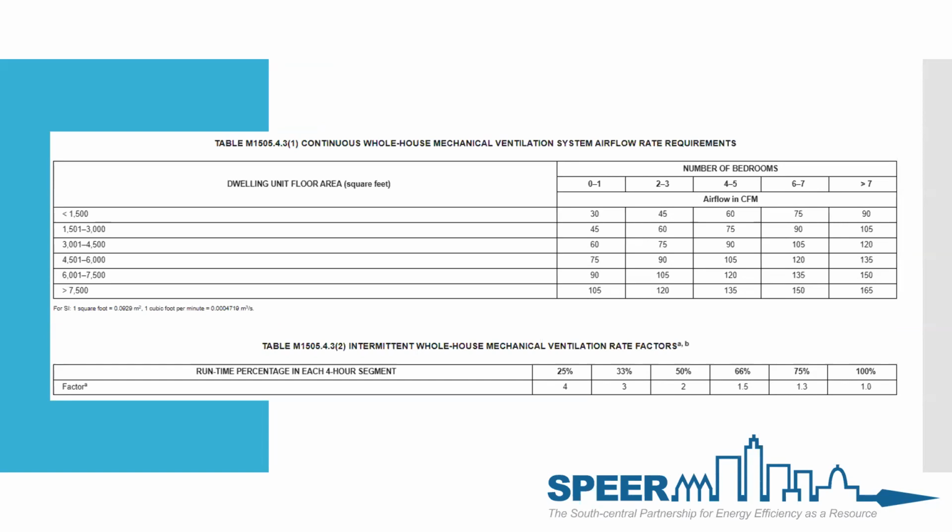We've talked about it before. One is this table. Two is actually doing the calculation, which is the ASHRAE 62.2, which I don't show here, but it's using 1 CFM per total square foot area plus 7.5 CFM per person. That's making up what is the minimum mechanical ventilation that needs to be done. So on using this table, when you have either method, the requirement says it's to not be less than the calculated CFM or the CFM listed on this table. In other words, when the system is being tested, the CFM reading should be at or above the listed calculated